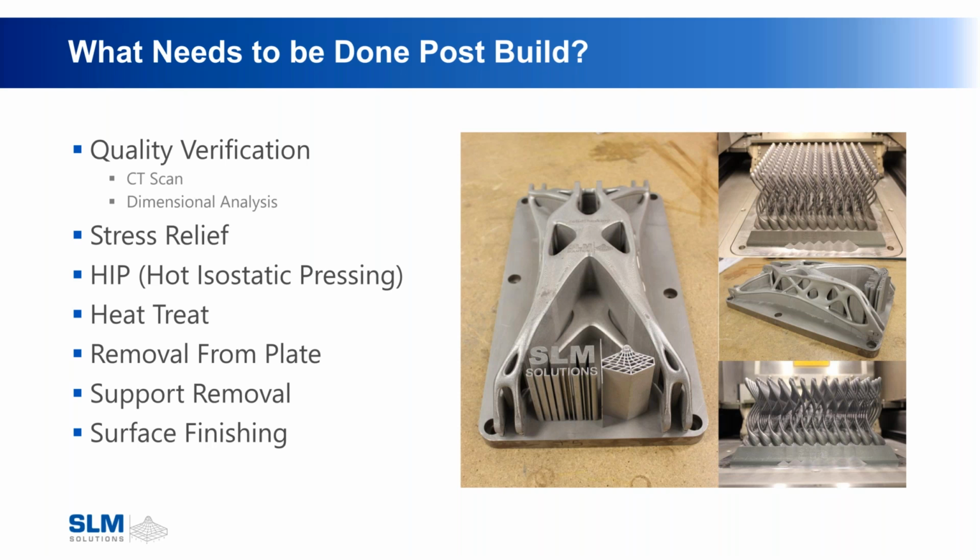There's what looks like a very organic bracket. Though it's very organic, there's a lot of support material within that part. You can see it on the picture on the left and the middle picture on the right. There's a lot of support material that needs to be removed. Now, that may not be the best orientation. That part can be changed.